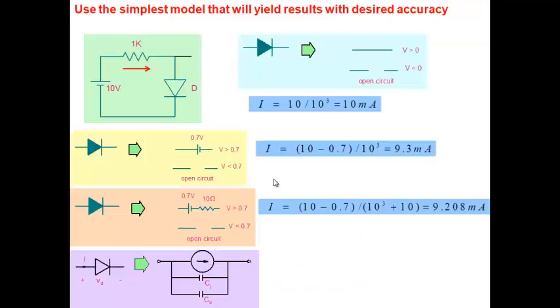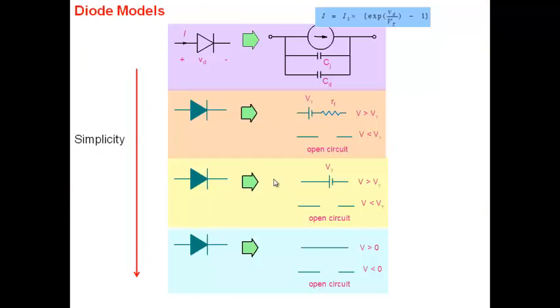Minor points, which is basically that we have seen that for a diode, and that's true for any element, we can build a range of models here. We saw a model like this, a more accurate model with an exponential characteristic, with a capacitor here, junction capacitance and diffusion capacitance. For DC, instead of taking an exponential, you could approximate it by a battery and a resistor and an open circuit here. If you want an even simpler model, you approximate it by simply a battery.